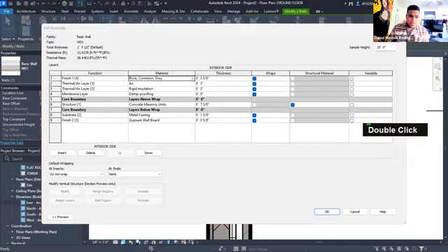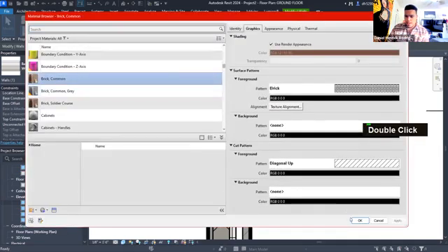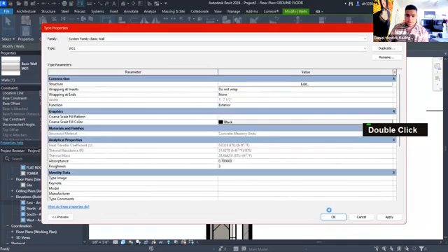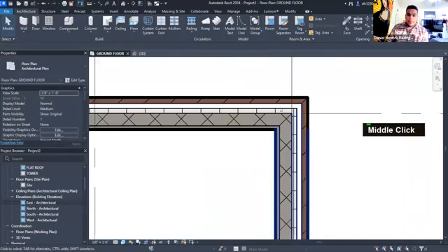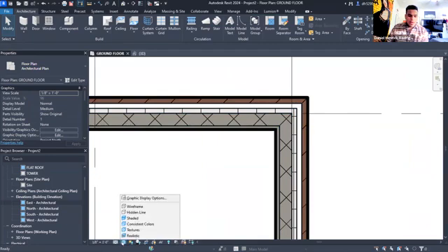very gray brick. So I'm gonna go back to the red just to show you guys, for the modeling, for you to be easier to understand the levels, right? But having the color gives you this idea of what's where, right? So we changed our detail level from coarse to medium, the display option to consistent colors.